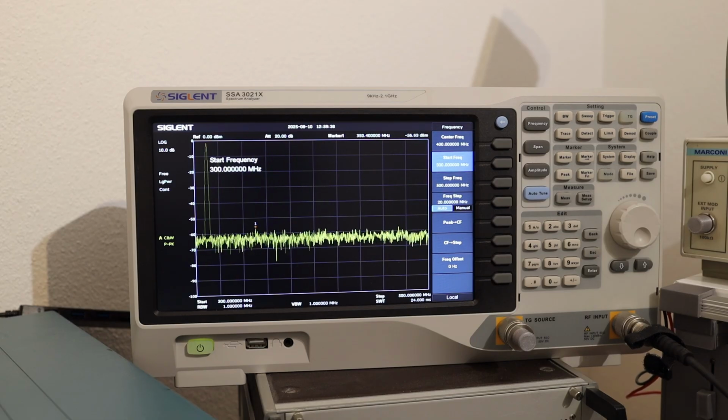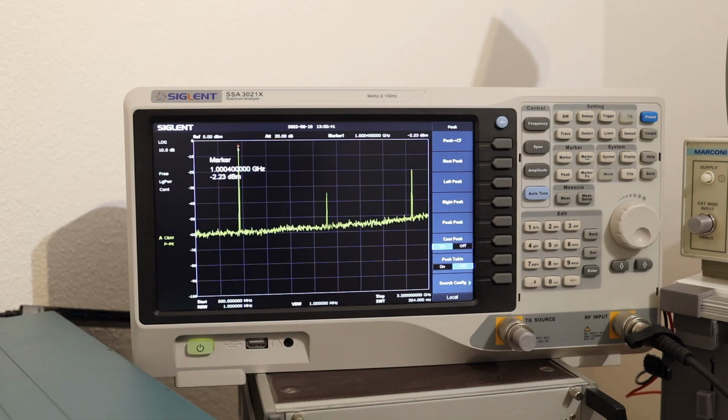Now I'll change the signal span or spectrum analyzer view to 500 megahertz to 1.6 gigahertz, and we'll see how it works there. And now change the span to 500 megahertz to 3.2 gigahertz and select the frequency of 1 gigahertz, and you see at 1 gigahertz it is showing the output around minus 2.3 dBm into 50 ohms load. And let's set it to 2 gigahertz.